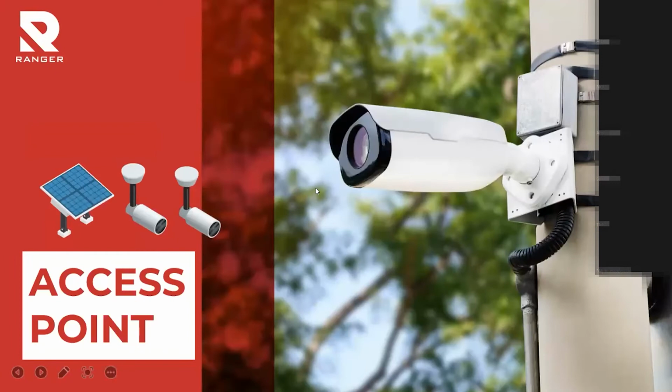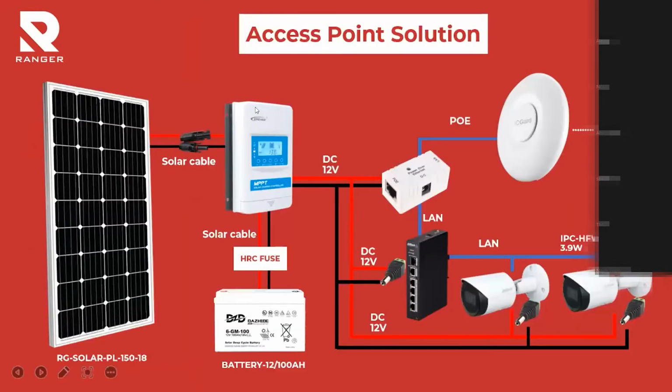So for the access point solution, this is the connection. As I explained before, the solar cable connects to the solar controller, the MPPT controller, using this connector and solar cable. The battery connects with the controller using solar cable, and for safety, we use an HRC fuse because a fuse is easier to troubleshoot if there is any problem.